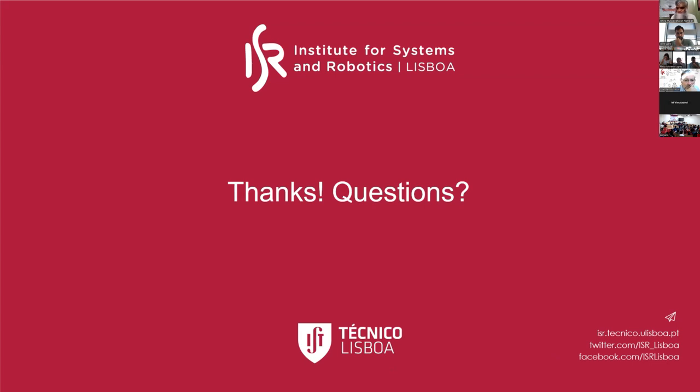Yeah, you are totally right. We are trying to explore those things now. The main missing part here is tactile sensing. You need to know how much force you are executing, measuring both things, to decide if you have to close harder or not. We are exploring that. In the first video that I showed, it was just closing with a predefined force. So if the object was too heavy, it was not able to grasp it.